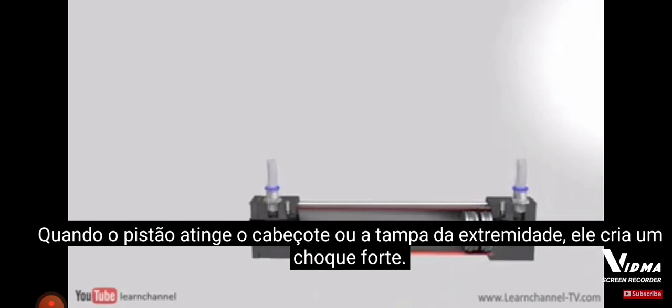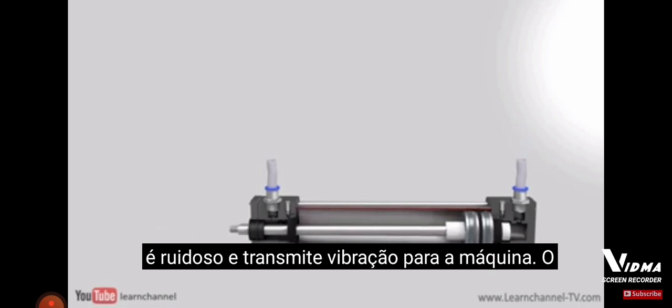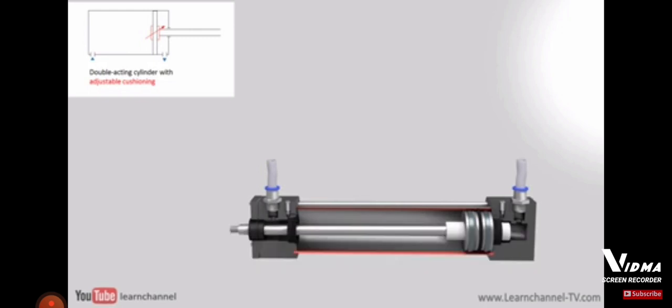When the piston hits the head or end cap, it creates a hard shock. Besides the stress on the cylinder components, it is noisy and transmits vibration to the machine. Cushioning is a possibility to decelerate the piston in the vicinity of the caps to prevent these hard shocks.